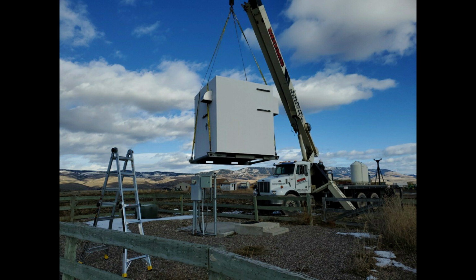Some airports have licensed Unicom operators that can also contact ATC on your behalf and, in turn, relay your clearance from ATC. You are also allowed to depart the airport VFR, if conditions permit, and contact the controlling authority to request your clearance in the air. If there is a direct line to the controlling ATC facility, the phone number is published in the ChartSupplement US, formerly Airport/Facility Directory, A/FD. As technology improves, new methods for delivery of clearances at non-towered airports are being created.